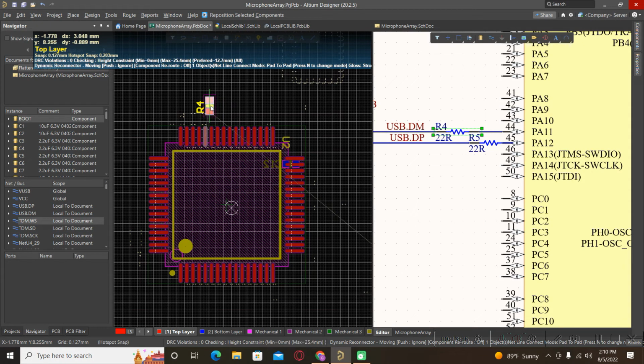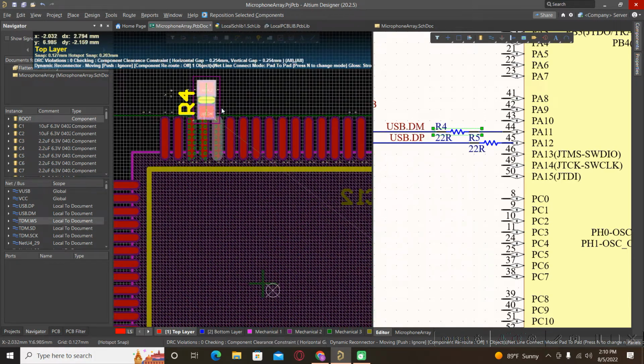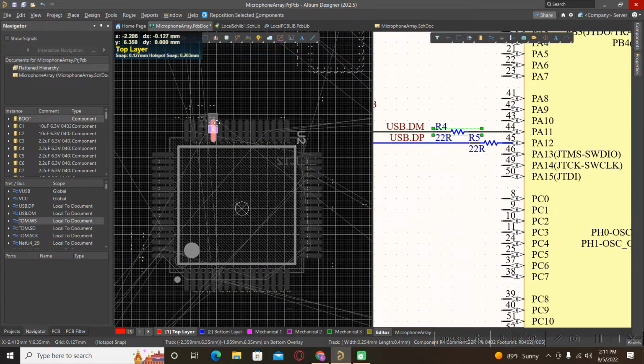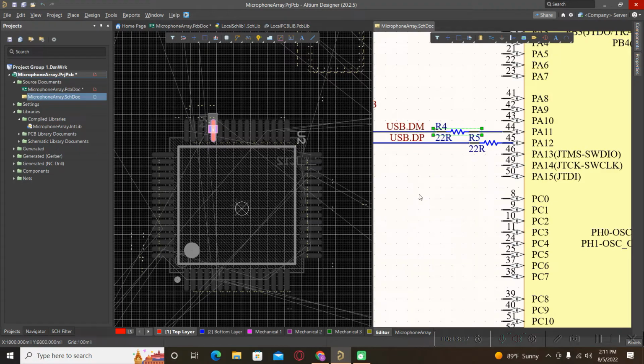And if you forgot to keep the shift button pressed, our mask disappears. And now hit L to switch to the bottom layer and place the component here, and our mask came back to the selected mode.